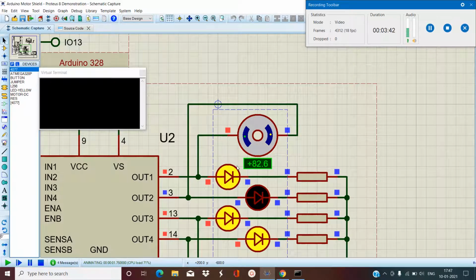It will run till it gets a constant speed in revolutions per minute. This will take time. Here, as you can see, the motor gets a constant speed of 459 revolutions per minute according to the PWM given of 255.